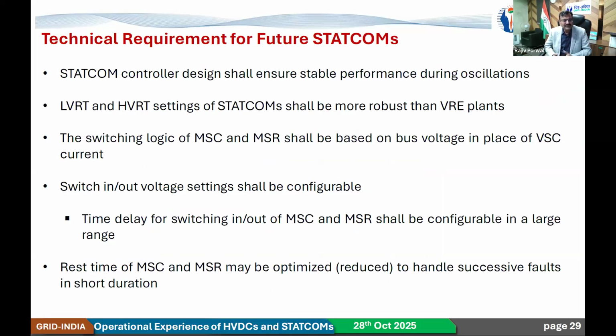So STATCOM controller design shall ensure stable performance during oscillations. LVRT and HVRT settings of STATCOM shall be more robust than those of VRE plants. And the switching logic of MSC and MSR shall be based on bus voltage, as we already have some STATCOMs which are based on bus voltage. So there is a lot of flexibility. We can switch the MSC and MSR on and off as we like. We can change the setting, but in case of current-based logic, we can't change any of the settings.